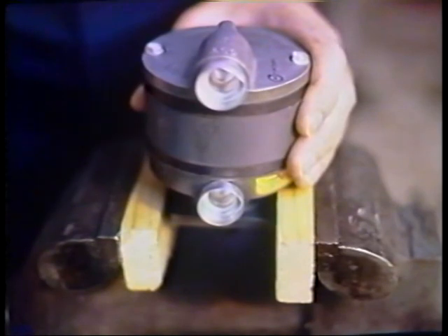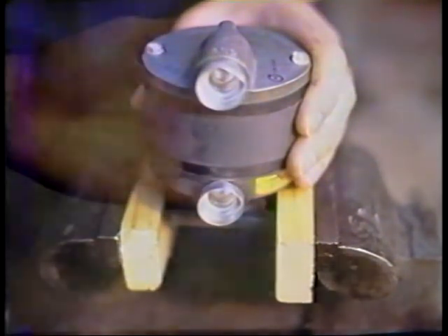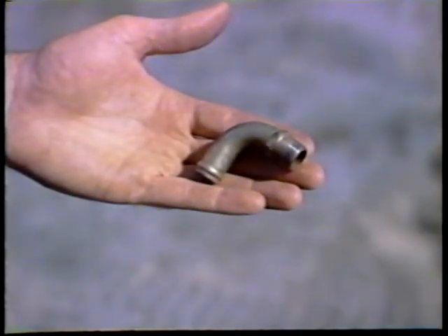To install the fittings in the pump, hold it in a vise across a mounting pad using either wood or soft metal jaws in the vise. Low-loss fittings are usually recommended during installation because AN fittings, with their smaller inside diameter and sharp corners around which the air must travel, have a more restricted flow.